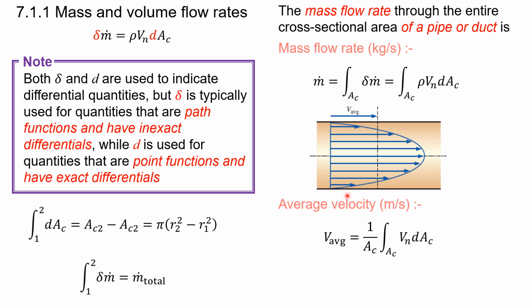Okay, important when we consider, because when we have a movement of fluid in a pipe, it will have a different velocity at different points. Closer to the boundaries, or closer to the pipe wall, the velocity will be lesser because of the no slip condition.